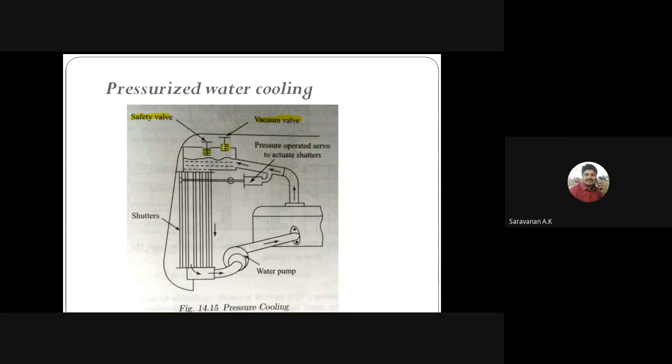At the first movement of the cap, it releases the pressure, which prevents the emission of scalding steam and the blowing off of the cap due to high internal pressure. You may have seen this many times: sometimes the radiator cap loosens and is blown off, due to this pressure condition.